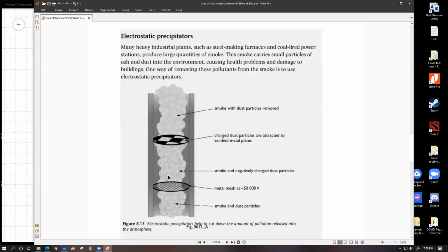You have to understand, as the whole thing comes from the very bottom of the chimney and goes up, all of it becomes negatively charged, and only the large dust particles, ash particles or solid residues get stuck over here. But the basic gaseous molecules, carbon dioxide, sulfur dioxide, nitric oxide, nitrogen dioxide, or even H2O steam molecules, oxygen, basic nitrogen, all of those can pass through without any trouble. So it's important that you understand that all of these things are negatively charged over here, not only the dust particles. Do I make sense so far?